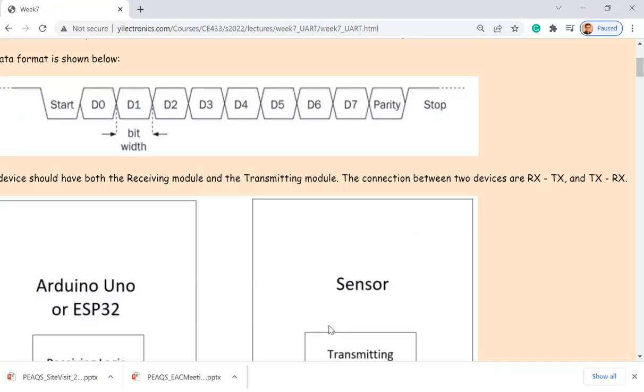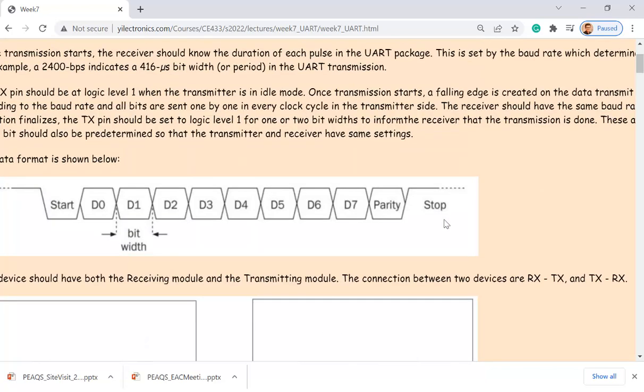How does that work? You are thinking, how do you know it's a stop bit? It's just a regular bit. It can be a data 1, right? How do you know it's a stop? With a counter, you know where to start. So start has to be low. So after the start bit is received, you just count 8 times, right?